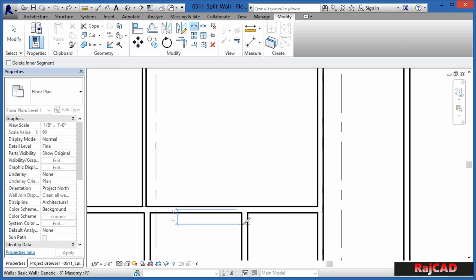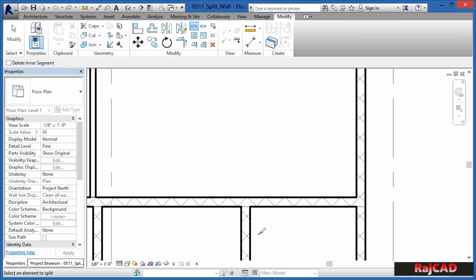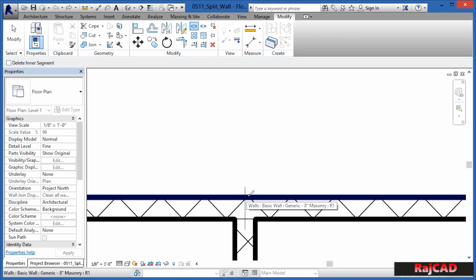It'll no longer ask us to click twice to create an opening. In this case, we're only going to click once. Now, move your X-Acto knife blade until this one line goes straight up and down, right in that location, right down the center of this wall. When you're there, click. It doesn't look like anything has happened.